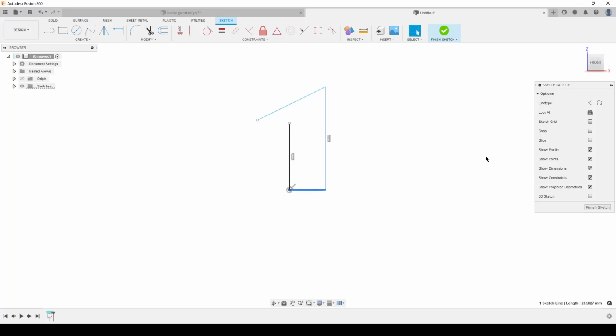This line here is just for construction, so let's go to construction. This here is our center line, so let's make it a center line. We're going to use midpoint from here to here. That locks things down nicely, like that. And let's start with our height. So this here is going to be the highest part of the cam. Let's do it like 80 millimeters.